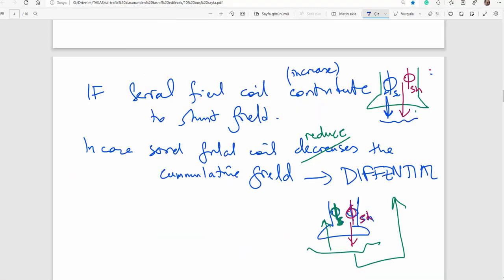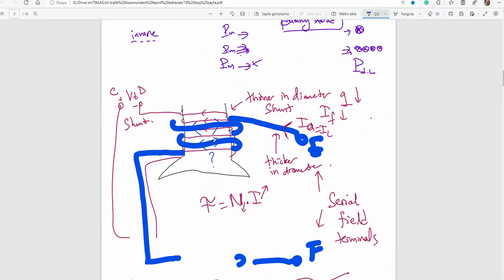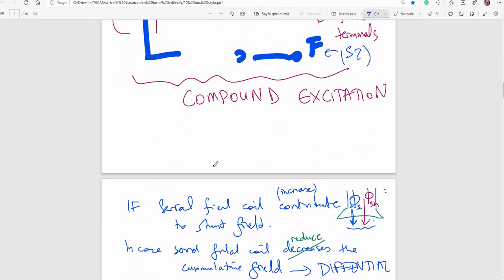On a single pole, you see, here are 2 different windings. One is E and F in old terminology. In new terminology, it is S1 and S2. That is C and D in old terminology, and in new terminology, it is field 1 and field 2. Those are the terminal labels.